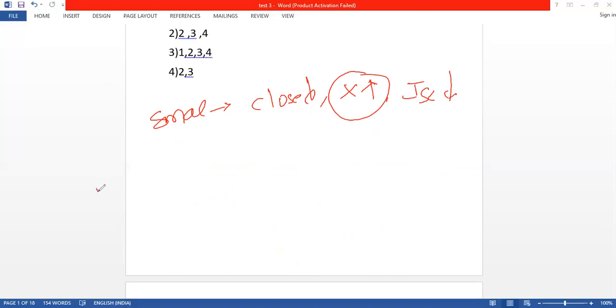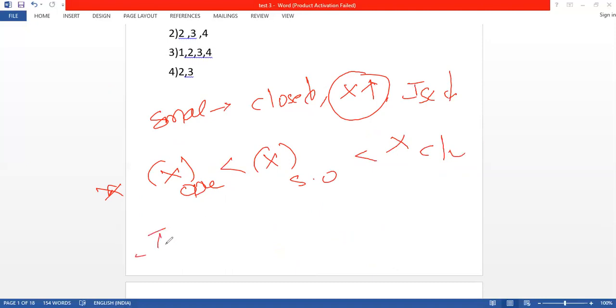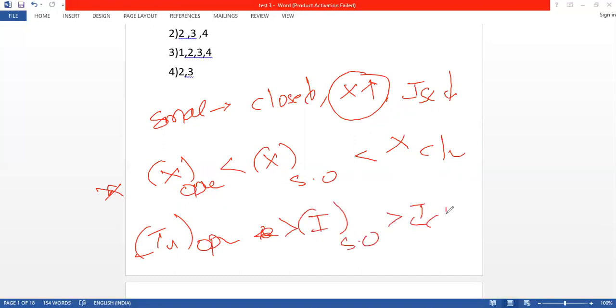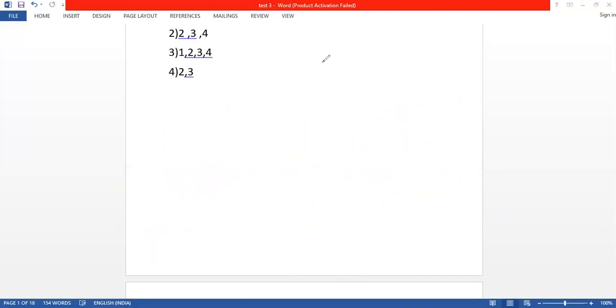So you just write down here: X of open is less than X of semi open, less than X of closed. Again, if you want a few more: I mu of open is greater than I mu of semi open, greater than I mu of closed. It will depend on power factor; it will have poor power factor. So induction machine uses semi open. Why not closed? Because placement of windings and cooling will be difficult. Hope you have understood all these points related to point number 1.